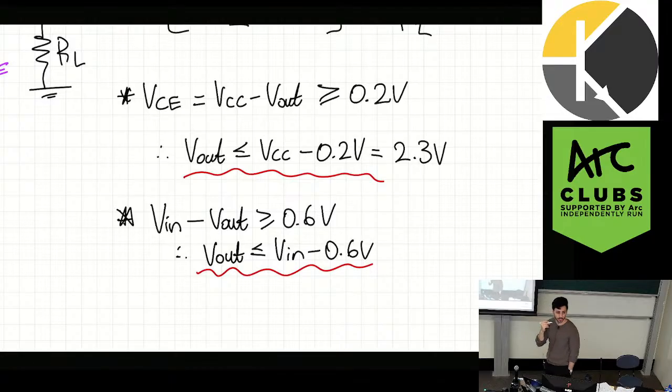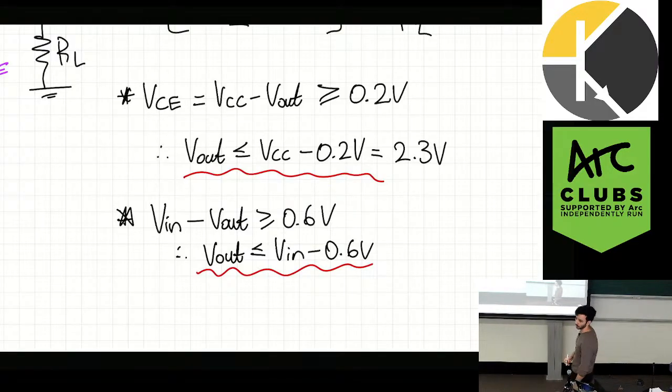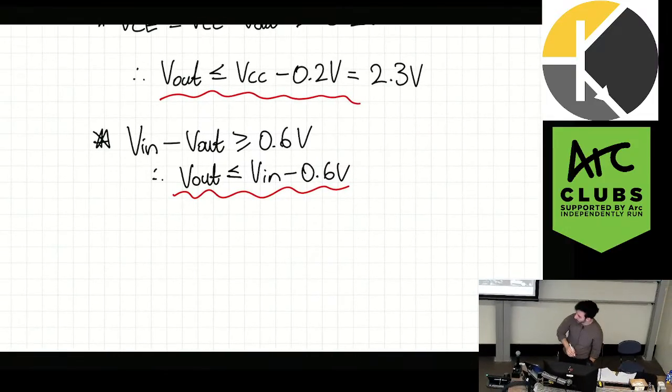From the other transistor? Yes. So we're going to use that to determine the lower bound, but it's not related to Vn. Also the requirement is equal to 0.6 volt, not greater. Oh, it's the same thing. It has to be above 0.7 volts, essentially. I don't think equals is quite the accurate way of writing it. It should be greater. So Vn. So what's the largest voltage Vn can be?